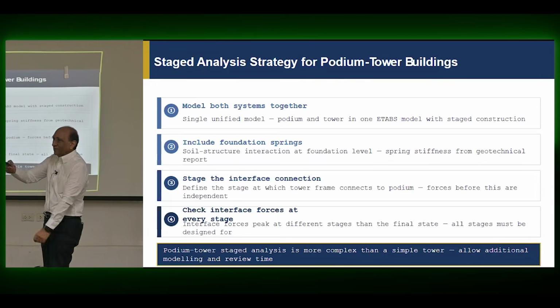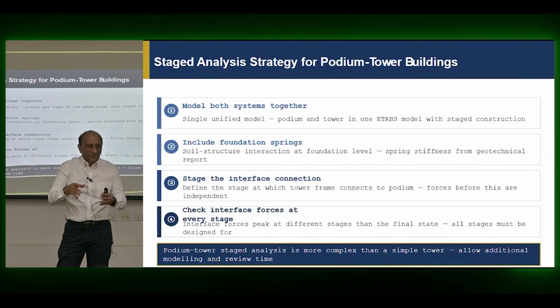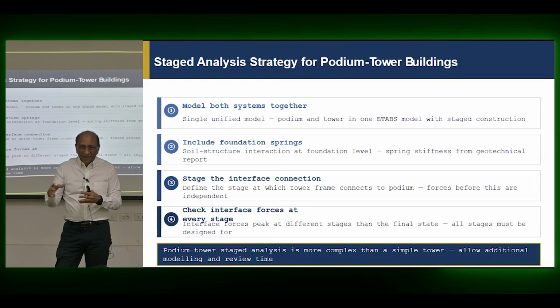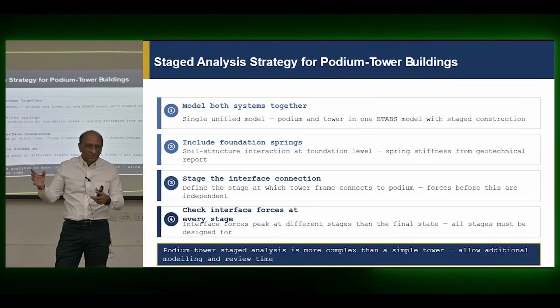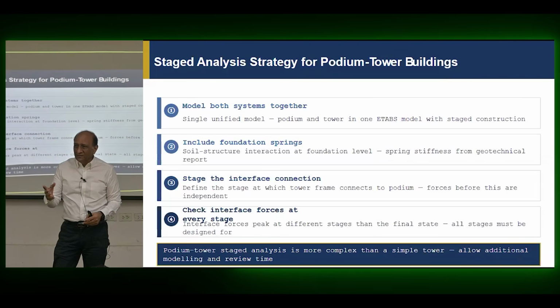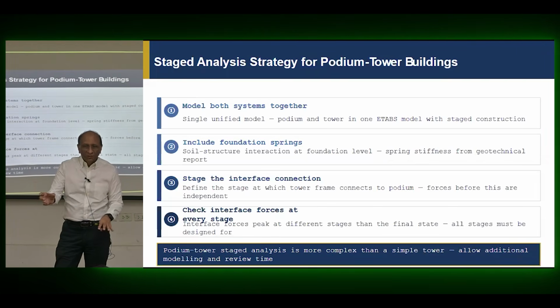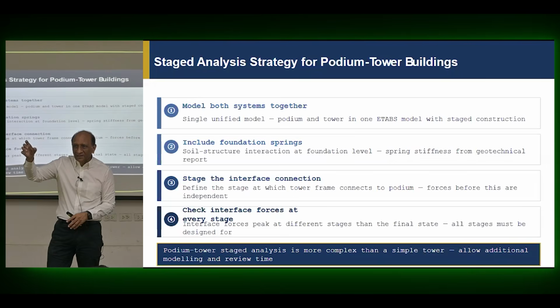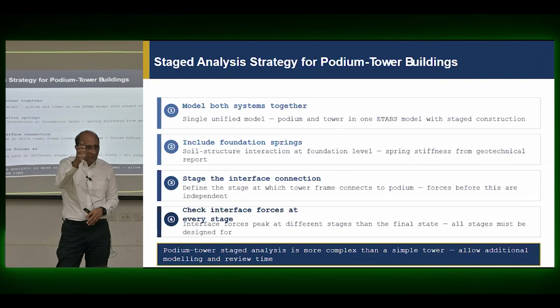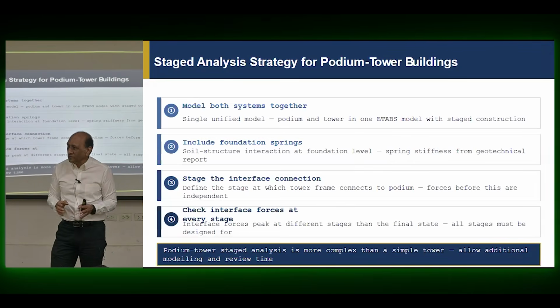I remember one building in the Philippines we did that has 3 towers and a podium. The construction of each tower came after another, after 3 years, after 5 years. And we had seismic analysis. You have all these kinds of forces in the podium design, a lot of things. We did the same thing because each tower has to be constructed. So the podium is done, only one tower exists for 2 years, then another tower will come, then another tower will come. During that, earthquakes will keep coming, right? So you have to be able to handle all those scenarios.